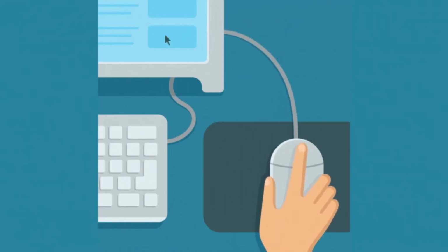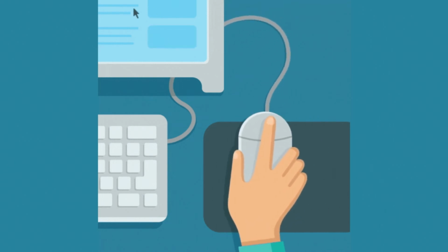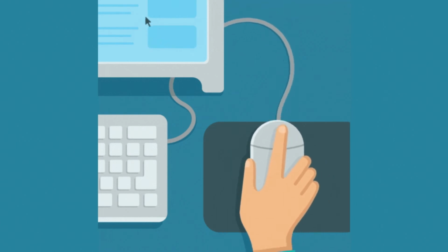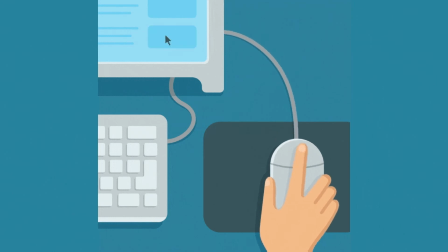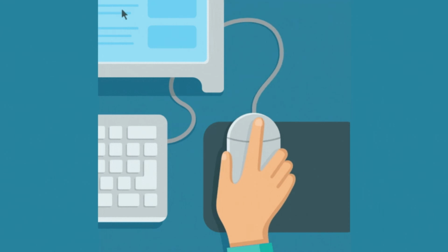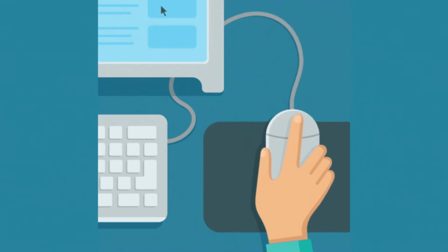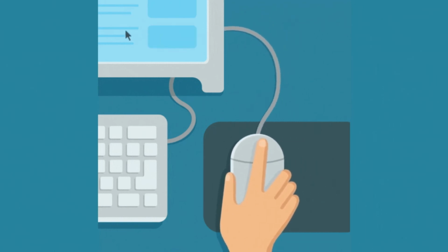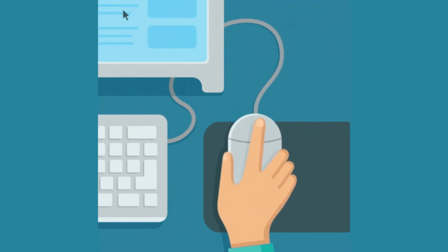Consider a computer that needs to determine whether a USB cable is plugged in. When you plug the cable of a mouse in a computer's USB port, circuitry in the mouse uses the voltage provided by the port to pull up the voltage in the cable above 3.3 volts. In the computer, a transistor detects the high voltage and translates it to 1 or on. This bit of information tells your computer that the USB device is plugged into the port.